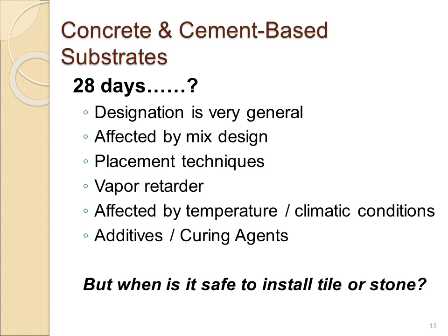Affected by temperature. Years ago, we had a contractor from Norway tell us that he installed tile in November, and when the concrete slab cured, or it actually unfroze in April, all of his tile failed, because the concrete now is going to change because of the amount of moisture that's in it after freezing for so many months.